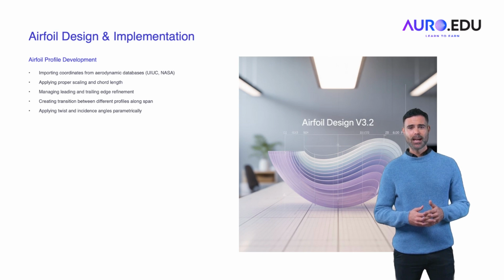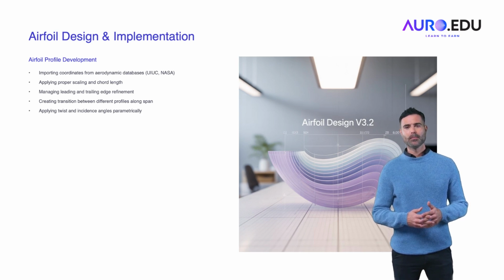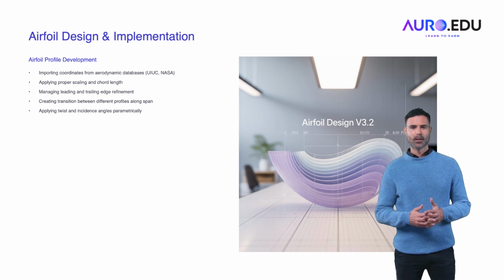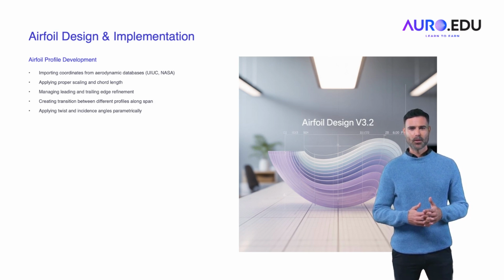Leading and trailing edges must be refined to ensure smooth airflow, which is critical for reducing turbulence and improving fuel efficiency. Twist and incidence angles are applied parametrically to optimize the airfoil's performance across the entire wingspan. The precise implementation of airfoil shapes is key to achieving the necessary aerodynamic performance, and small changes in airfoil design can significantly impact the flight dynamics.